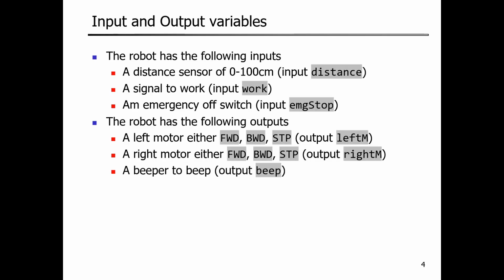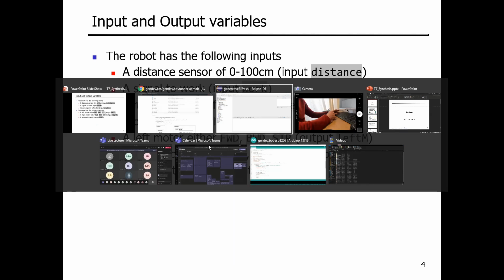The task for today is a reactive system, so it is a little different from what we did with the state machine. If you remember, for the state machine, we were handling events. We would check the sensor every 50 milliseconds, but we would only call the event for the robot being close to an obstacle if we were really close, less than 20 centimeters away. Only then would we call the actual event, which would fire a transition, and then we would be in a state, and if the state is not listening to the too close event, then nothing would happen.